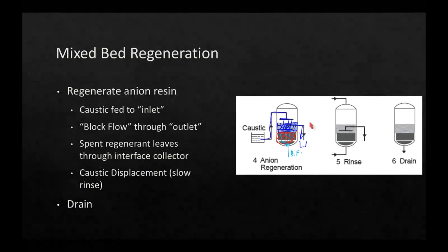So then after we've done this, what we're going to do is a displacement. And displacement is a very slow rinse. So we got some water coming in there, we got water coming in there, and they're both pushing very slowly. They're pushing their respective acidic and caustic leftover regenerant toward that interface collector and out to waste. That could take a little while.